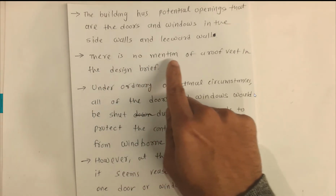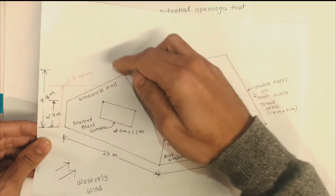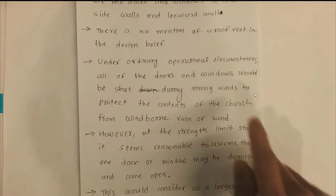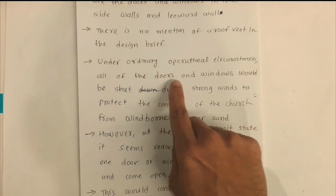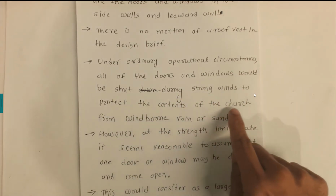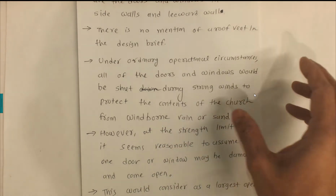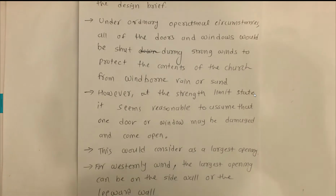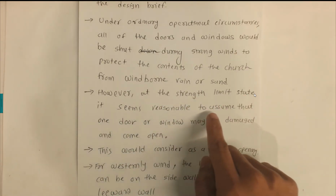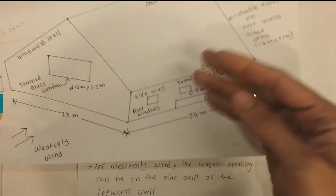There is no mention of a roof vent in the design brief, so there is no opening on the roof in the question. Under ordinary operational circumstances, all of the windows and doors would be shut during strong winds to protect the content of the church from wind-borne rain or sand. So in the general case, we assume they are all closed, a sealed building. However, at the strength limit states, it seems reasonable to assume that one door or window may be damaged or come open. So we can say that one should be open.